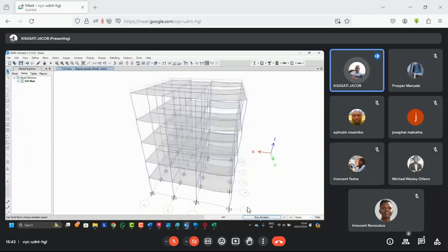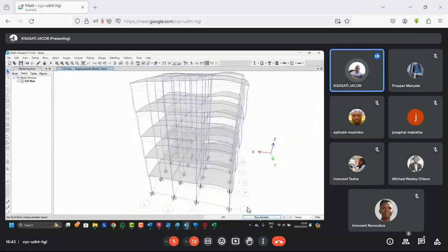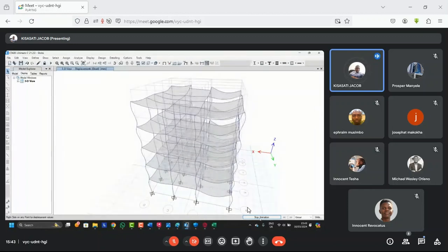So that is actually how the structure behaves when it's under the two loads. Now it will give you the deflection or displacement in millimeters. You can change the unit to anything that you want. But now, please listen to this, because this is the most important thing with ETABS and Prota Structure. I can only teach you that. Now you will be a perfect engineer. Now we have maximum and minimum deflection. As engineers, we always concentrate on maximum deflection.